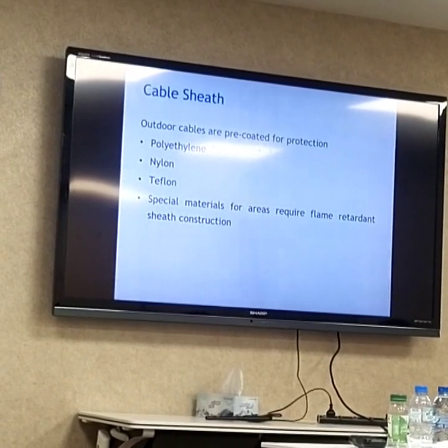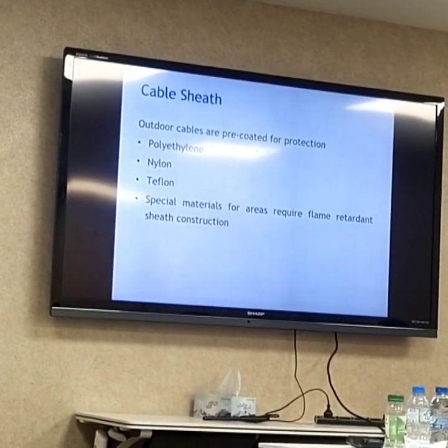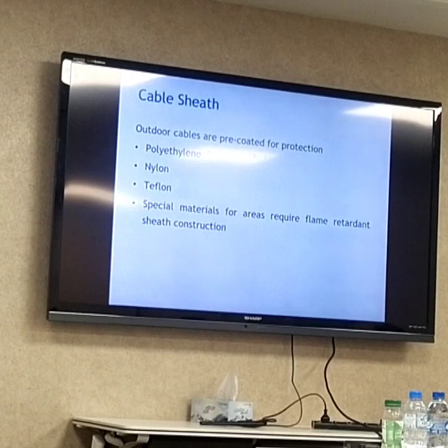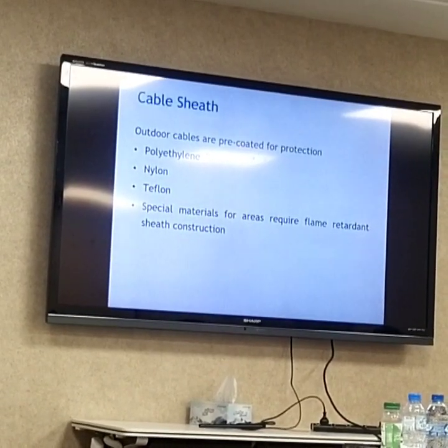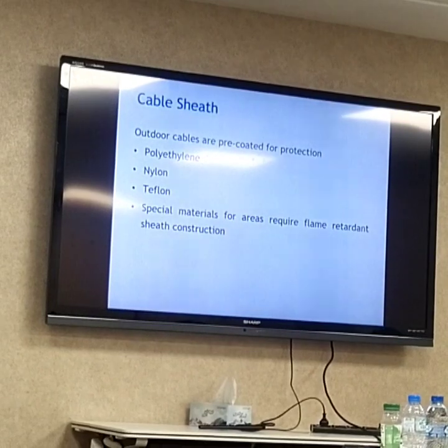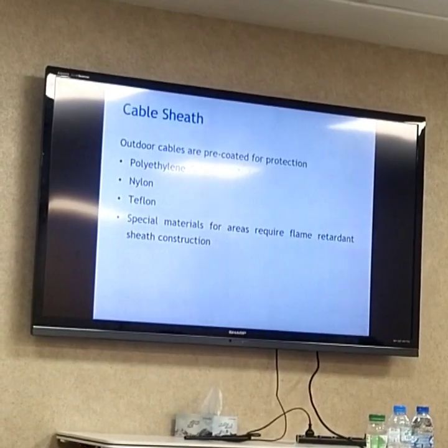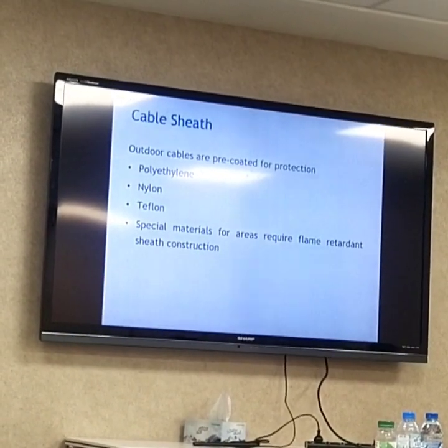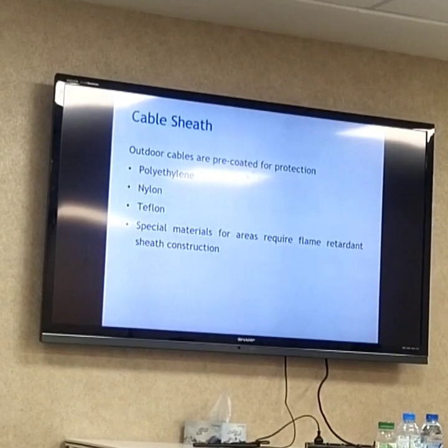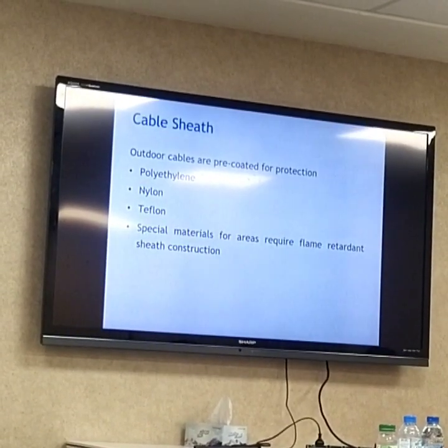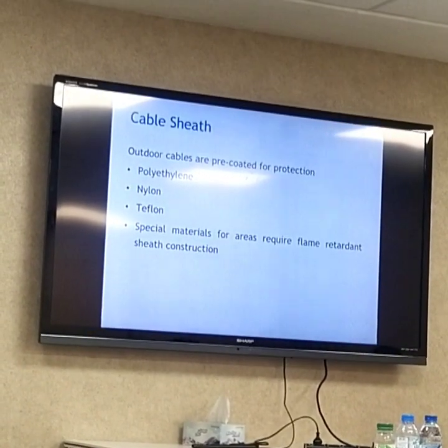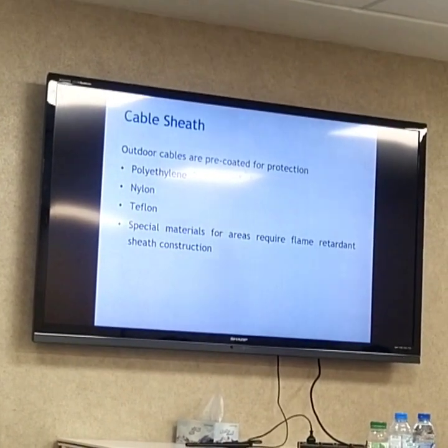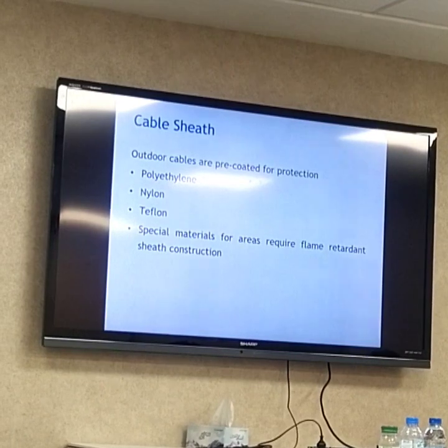Fire resistance cables like MICC or FB200 or FB400, this material can work under fire conditions. It will resist a fire. For example, the MICC cable can work for 2 continuous hours while it is catching fire. You can put it totally in fire, and it will continue to perform with no problem. This is fire resistance cable, cables that can work under fire conditions, and it can perform well even when it catches fire.